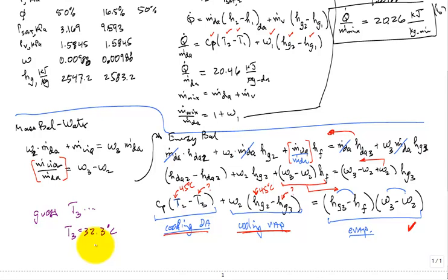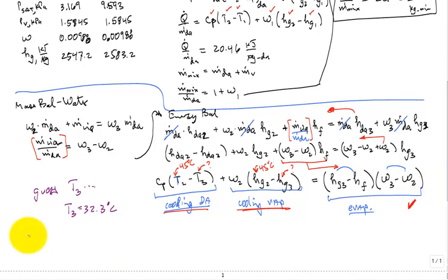And how did you calculate omega 3? Well, I know we substituted in here, but let's take a look. What would omega 3 again be? 0.622 times P_v divided by P minus P_v, and P_v is equal to the relative humidity at 3, times P_sat at 3.